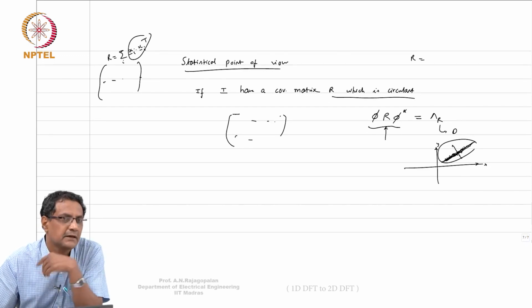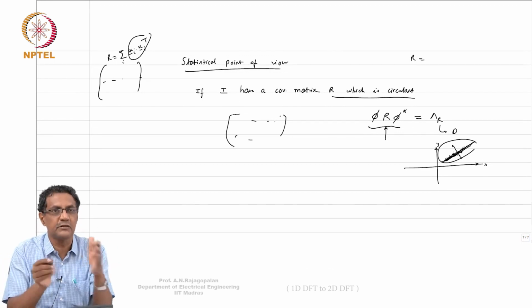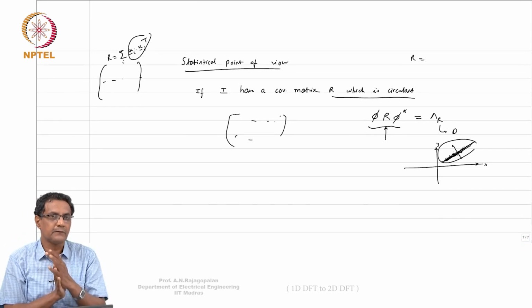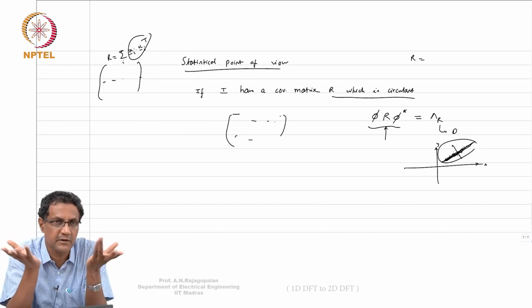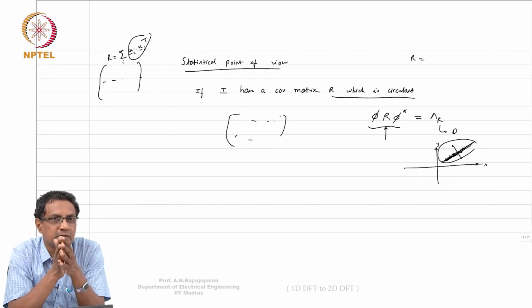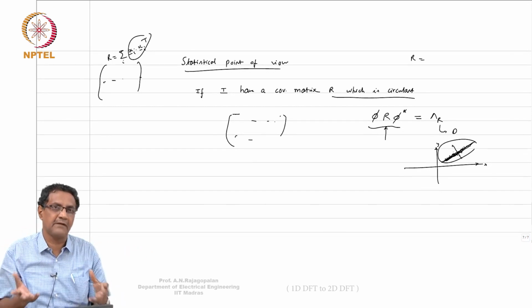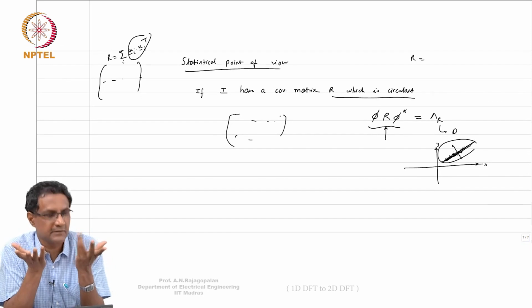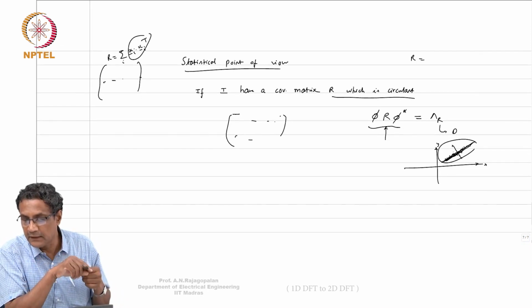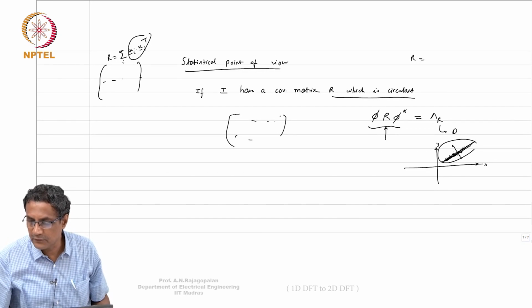What error you incur in a mean square sense, we'll see later. But this decorrelation is about all this. So instead of a standard basis, you reorient with respect to some other basis, and typically it's your eigenvectors. That's where your KL transform, PCA and all come in, because the best basis that will decorrelate is in fact the eigenvectors of that R.